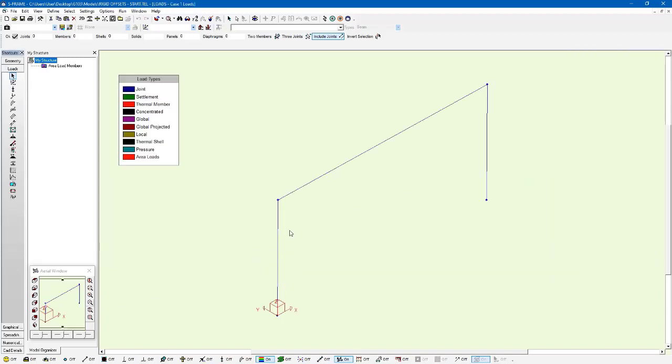And if I go to the loads window, we can also see that we have one load case. And this load case has two different loads. We have a UDL, a 20 kilonewton per meter UDL, and a 200 kilonewton concentrated load at the center of the beam. So we would need to keep those in account as well when we're actually modeling these rigid offsets.